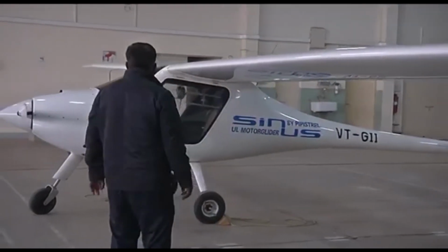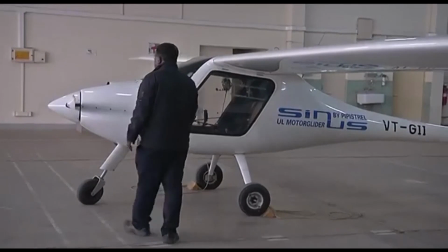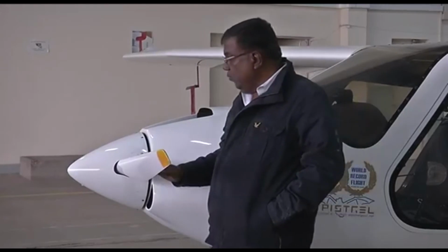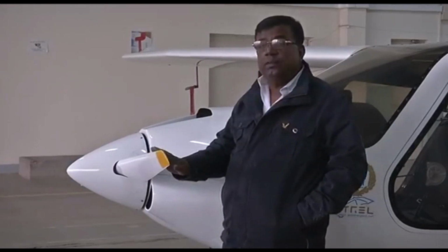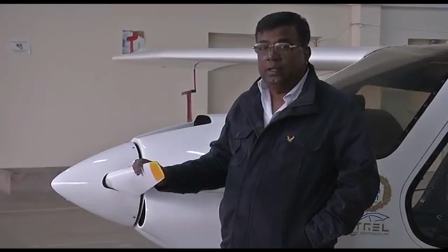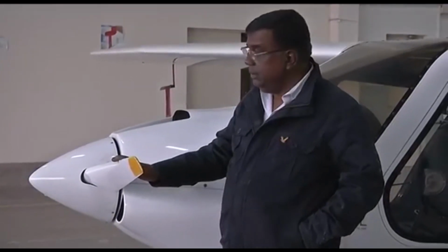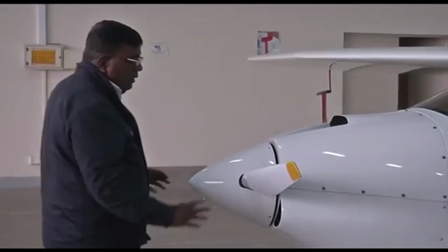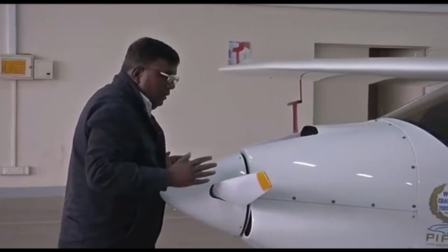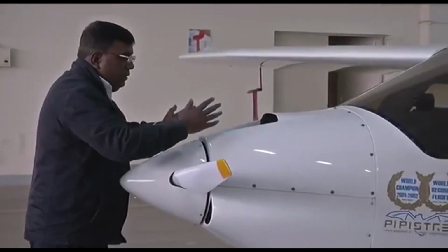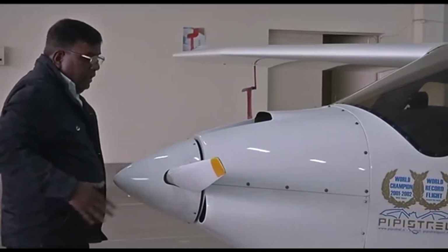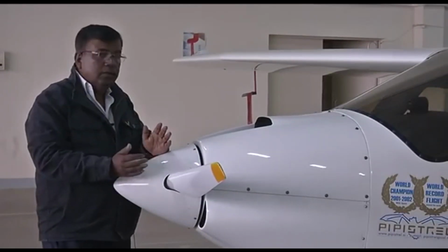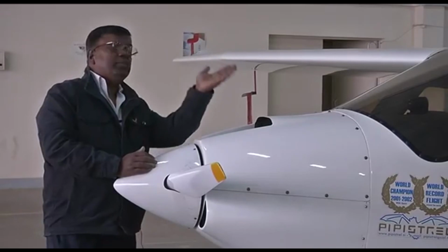And if you now come to the engine side here, which we have already discussed in the classroom, what is the contribution of this propeller to the longitudinal stability of the airplane, especially static stability? And you know, if there is an angle of attack disturbance coming here, then the thrust will have a direction like this, and there will be a normal component of thrust which will be a function of angle of attack in a loose way, and this will give a nose-up moment about CG.